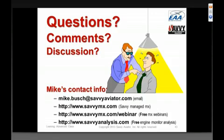It is not something that is a good idea to use as a leaning reference, for exactly the same reason that EGT is not a good idea to use as a leaning reference: to establish where peak TIT or peak EGT is, we have to dwell in that area that we really don't want to dwell in.